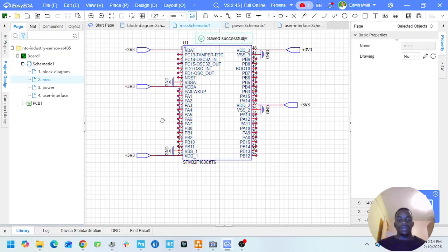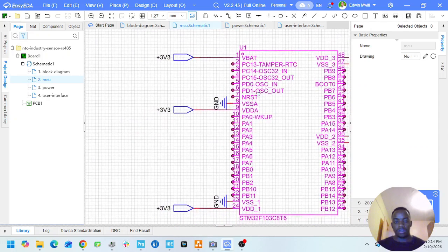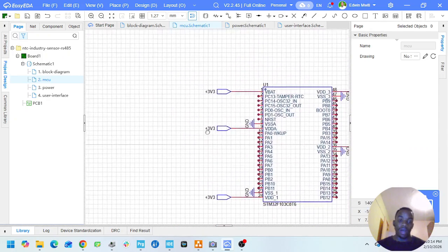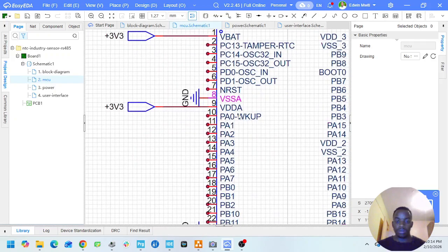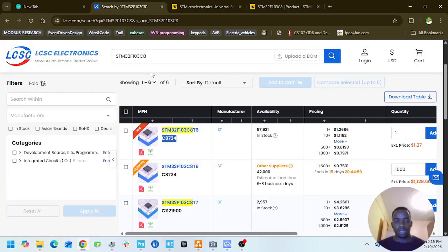Yeah, that's good. The next thing I do now is basically handle the power. There are several pins to do with the power. We have to filter using capacitors, right? So what I do is I'll take a 100 nF capacitor. I'll just come here and look for C005, 100 nF capacitor.